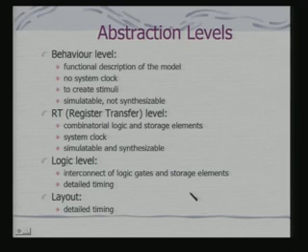In fact, if we talk about hardware, there are multiple levels of abstraction with which we can look at it. At the top level, we have what we call the behavioral level, which is a functional description of the hardware model. There may be no system clock. You want to create the basic stimuli, and this is simulatable.